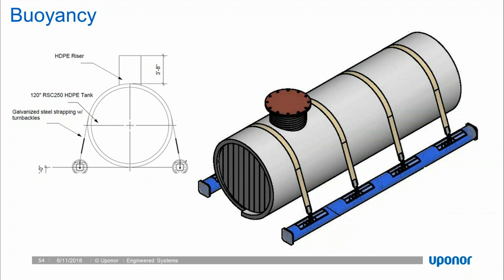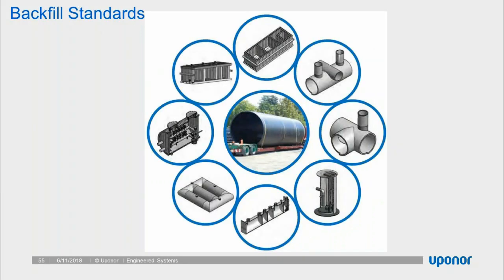It sets next to the structure, and all the contractor has to do is pour concrete into the tube that already has steel reinforcing and all the hardware attached to it. So it eliminates a lot of the guesswork for the contractor and gives them a turnkey system to counteract buoyancy. We provide this on projects when needed.